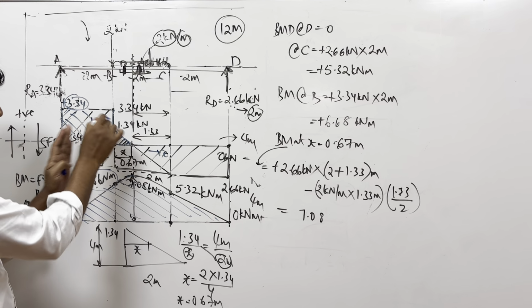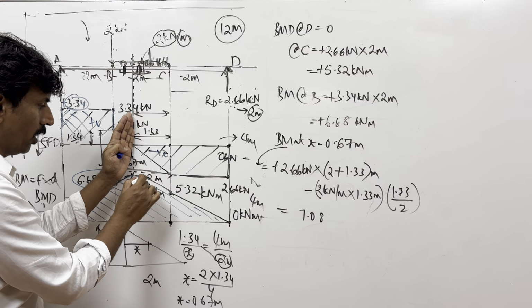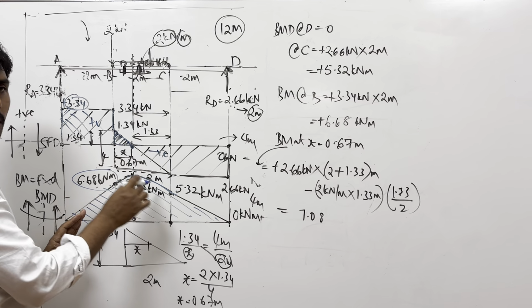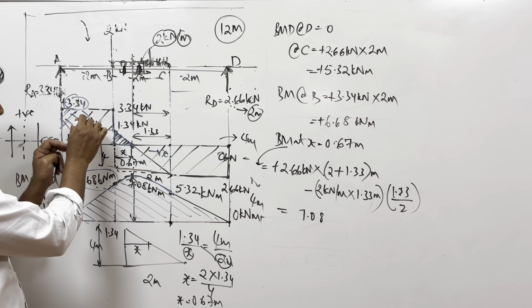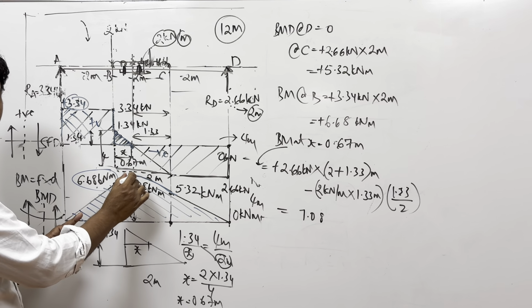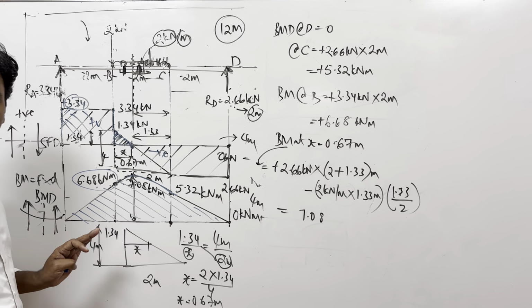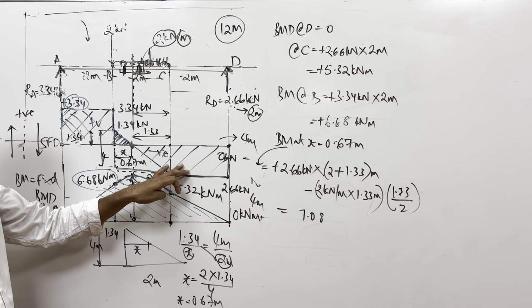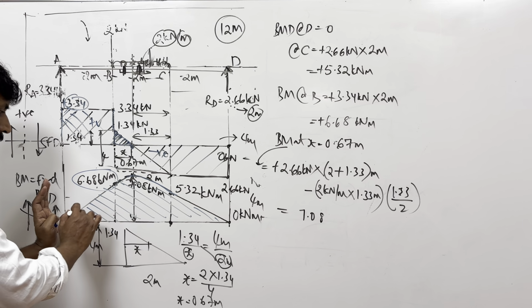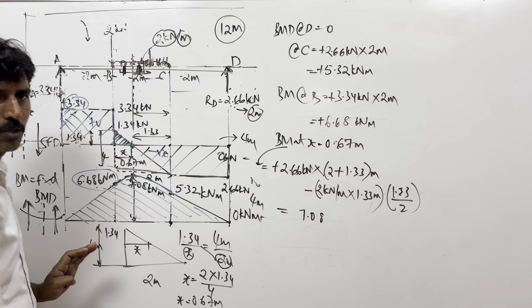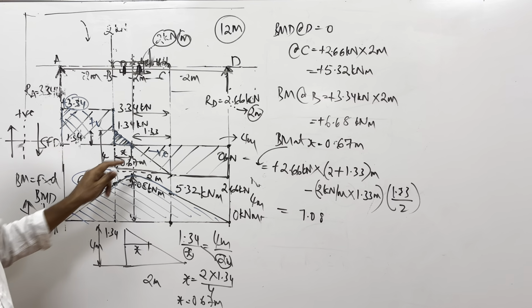From positive it will start going negative. So from this point it starts again decreasing. It is the reason where shear force crosses zero line, it will start going from positive to negative. So therefore it will reach a maximum point here, then it again starts decreasing. Okay, don't worry, decrease or increase. So basically decrease means the values that got added here. Okay, it will not go back below zero. Okay, it will start doing this.